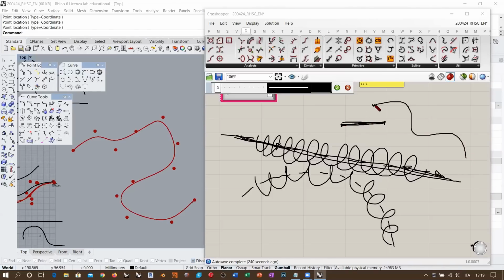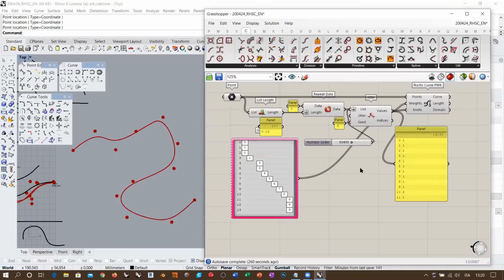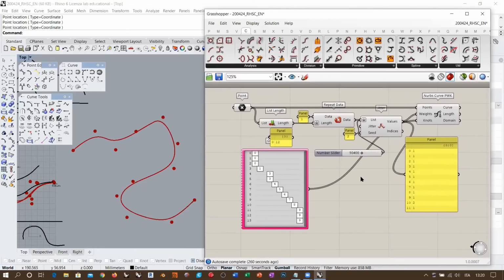You must take this line and eventually approximate it with a polyline, and each segment of the polyline can become a spring, not the curve. So it's just the way that the elastic problem is translated into an approximation via the ideal springs, okay? So it has nothing to do with topology. And the way you do it, of course, is by shattering the straight segments or converting a NURBS curve into a polyline and using the segments and so on.